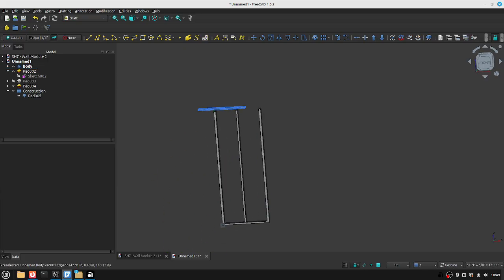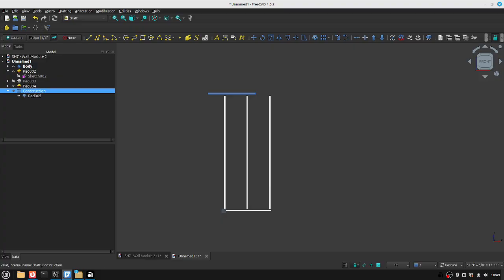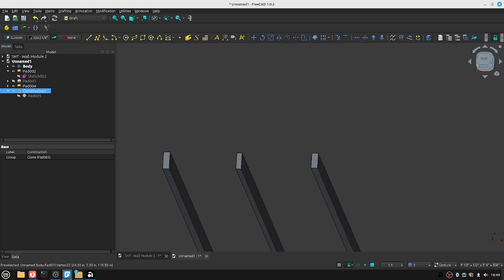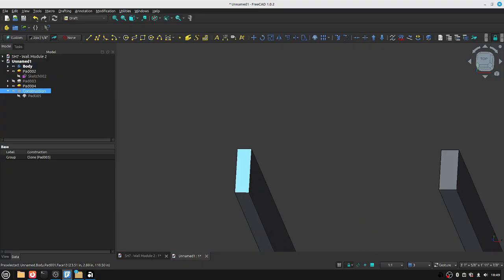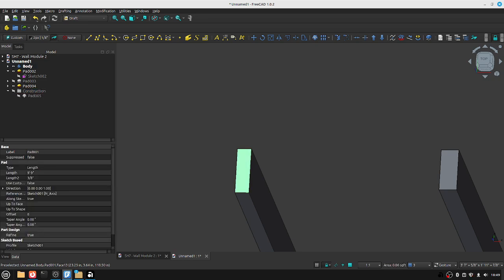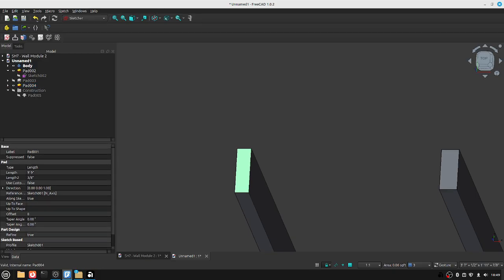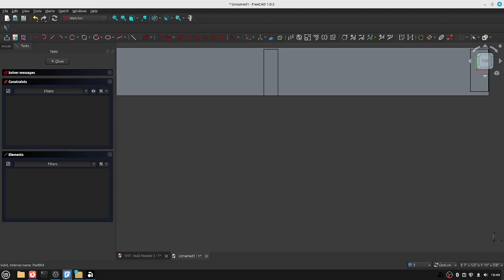But the simpler thing is what Keith said. Let's do that. I'm going to hide that. Just go to these and draw your top plate on one of these. Will it work? I'm sure it will. So I select one of these faces which are already on at that particular height. I'm going to just put a sketch on it. So I select the face. And the cool thing about the sketcher part where you select the faces is you don't have to work in this plane. You already selected the plane, which is the face. So here I'm going to go to sketcher and I'm going to just draw on it. Plane face, yes, it gets me that view.